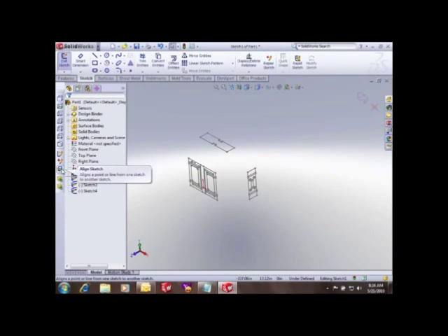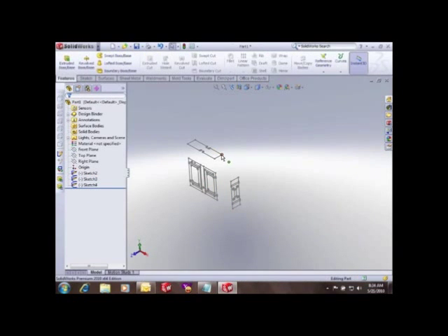And then we can align the views together using the Align Sketch tool. So I'm just going to pick what I want to move and then what I want to move it to, and I pick Align, and it aligns those two edges or lines or vertices together. So we'll pick those two on this view and align those. That way I can use those views to extrude up to and use the different sketches to cut with.